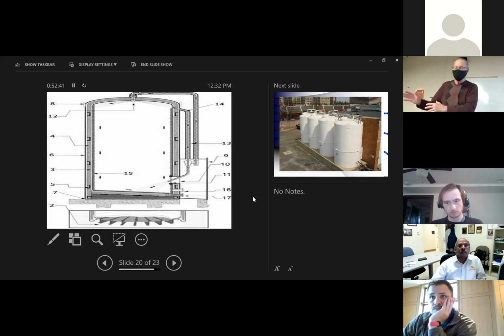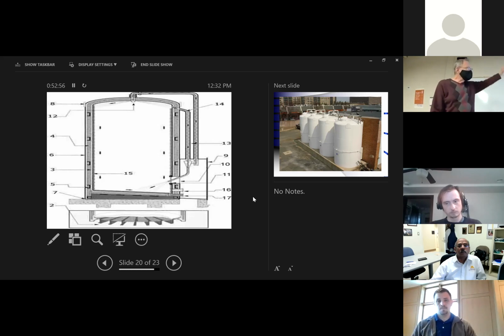If you need to cool something to put in these, you need to use some type of plate heat exchanger or tubular heat exchanger to cool that liquid down. What these will typically have is what's called a cold wall. So maybe 5 feet, 10 feet up, you'll actually have refrigerant so that as the liquid is slowly mixed in the tank with an agitator, you can maintain temperature.